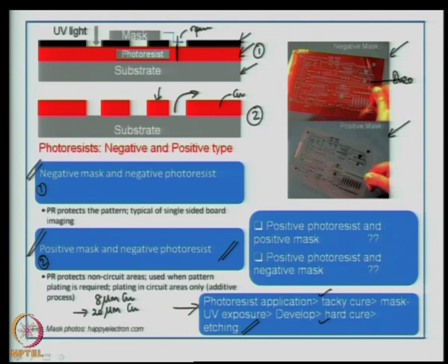The reason for the curing process, that is the tacky cure and the hard cure, is that the host material, that is the photoresist, should not lose its dimension, should not be attacked by the etchant chemical that is going to be used finally. So, as the name indicates, the photoresist should resist the etchant in some sense. So, that is why these process steps become very important.